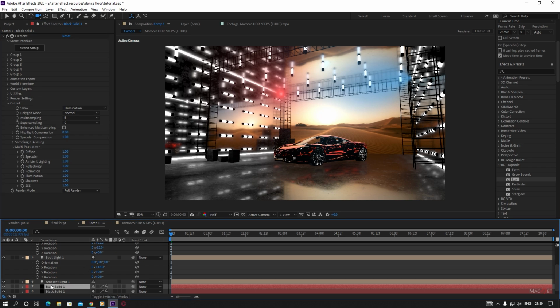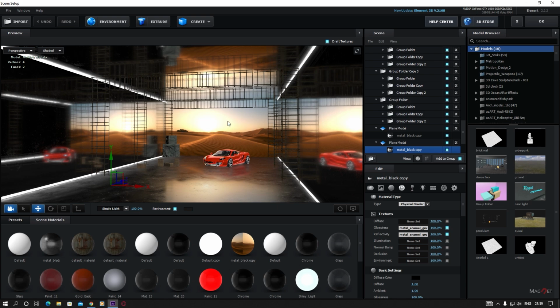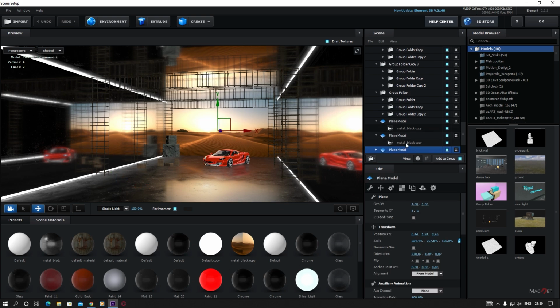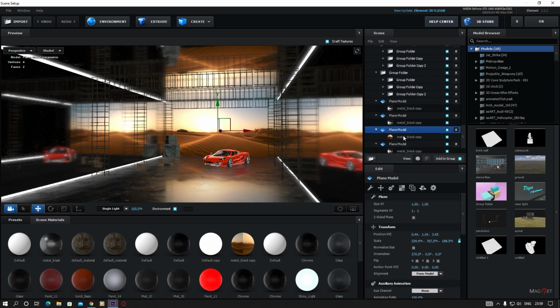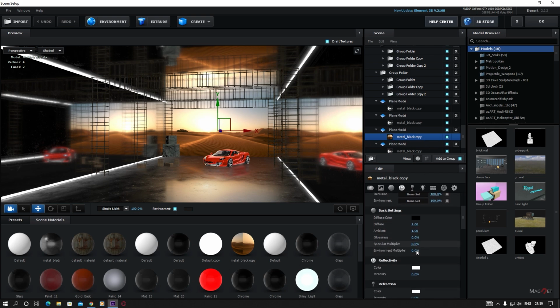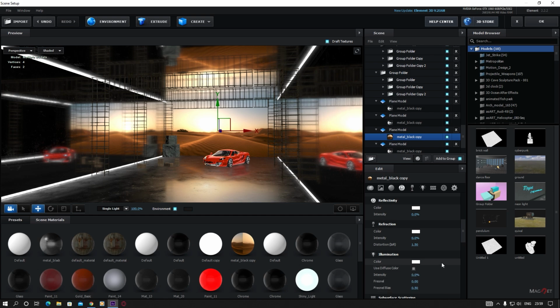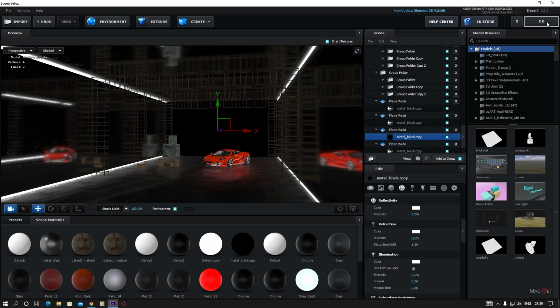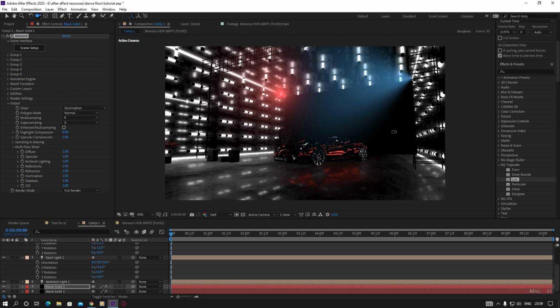And then we select this and go to the scene setup, and we don't want the illuminated part of the scene to show this background screen. So we select the background screen here and go to its material, and we disable the illumination, so just make it 0. In that way it will be black. So now hit OK, and this looks something like this.